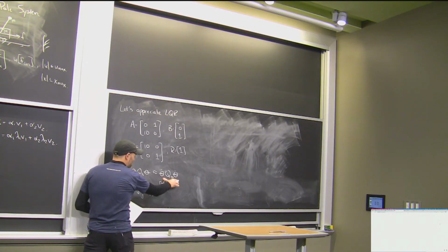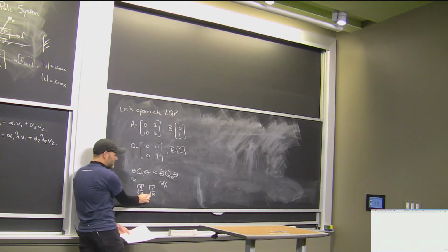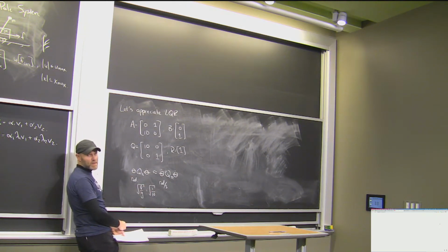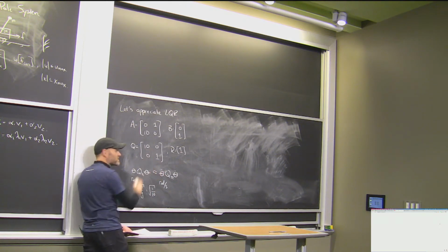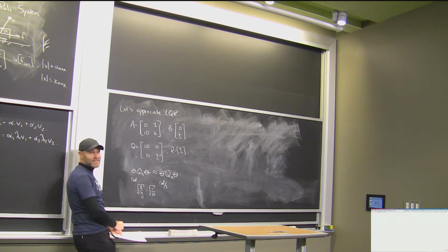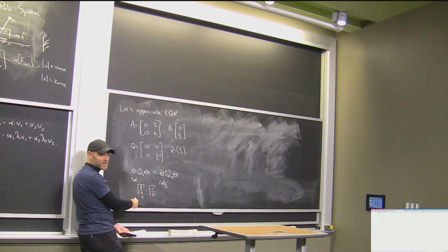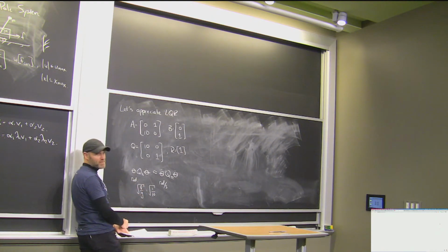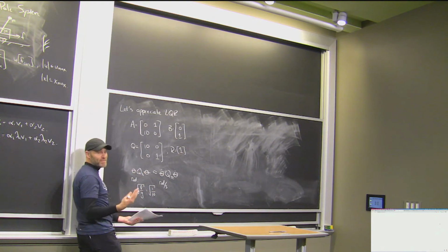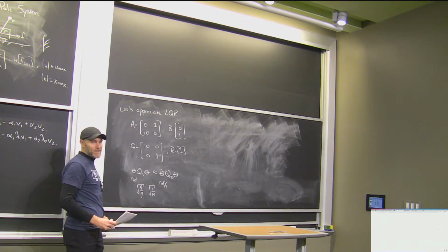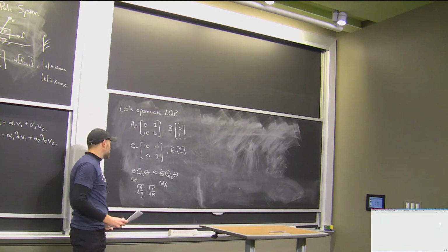If I stick in square root of 1/10 twice, I get 1/10, and it tells me I should be 10 times bigger just to make those units approximately the same, right? If you're working with robots that are in Earth's gravity and are about a meter long, that's a pretty good rule of thumb. Make your costs on your positions about 10 times bigger than your derivatives, right?